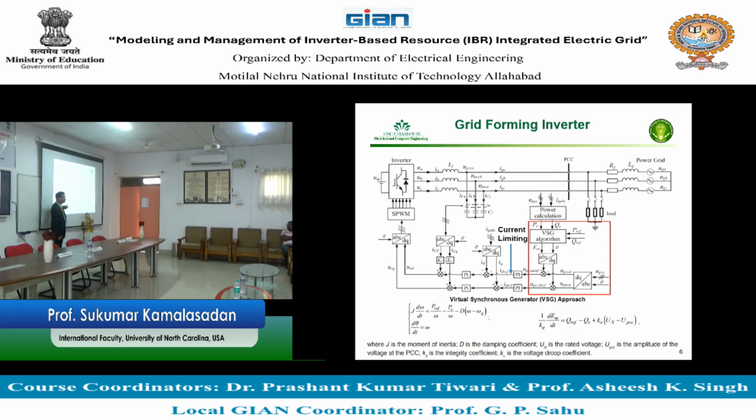Oh, can you also change D, damping? Yeah, you can introduce damping much like a synchronous generator, and put in the damping coefficient much like a synchronous generator. If you use this and try to generate the inertia for a frequency, this is called inertia emulation. So that inertia emulation is basically to get some value of inertia when you have an inverter connected. You understand the fundamentals? Yes.